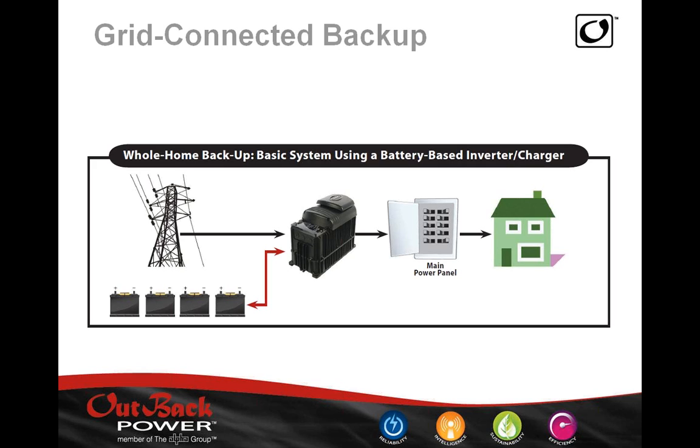The one thing that's very important to note here as we're talking to customers and describing this to people is that you don't want to back up the entire system. You really only want to back up the essential loads. The reason is that the bigger the system that you want to back up, the more the loads and the longer the running time, the bigger the battery bank is going to have to be.